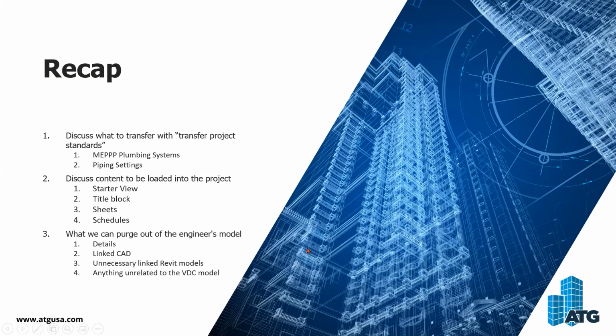Okay, and then finally we also discussed what to purge out of that engineering model, and this is very big. We're going to purge out things like their details. There's no reason that we have a ton of drafting views, especially if we already have a copy of the model sitting in an archive, and then we also have all the PDFs. So by having that stack of PDFs from them, we will definitely be able to resort back to that.